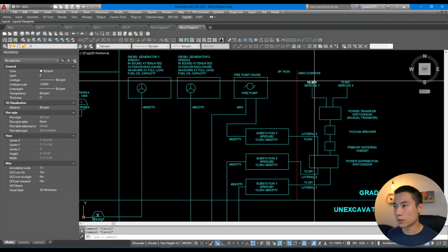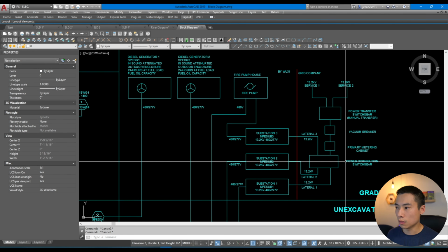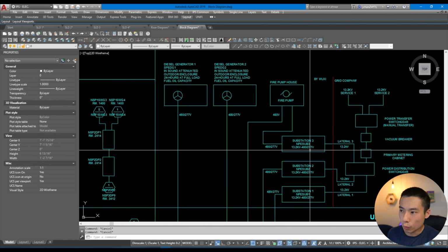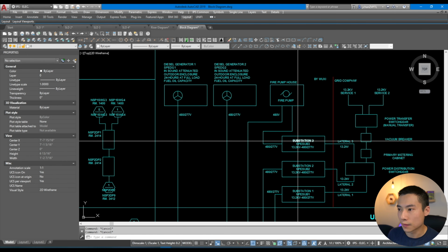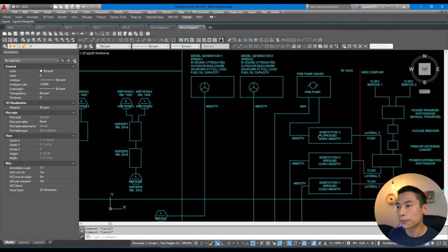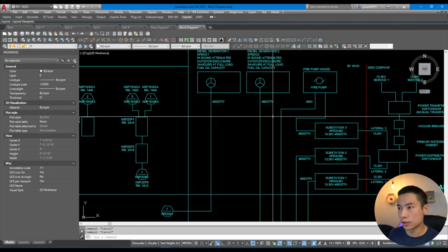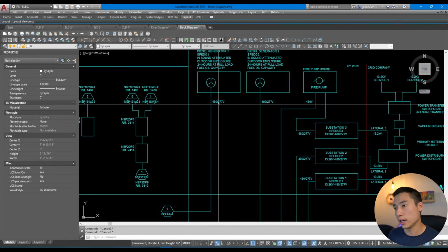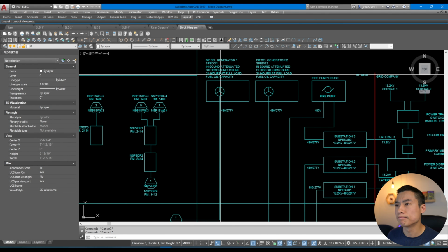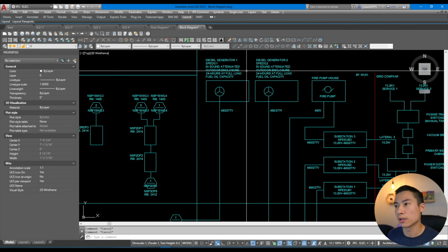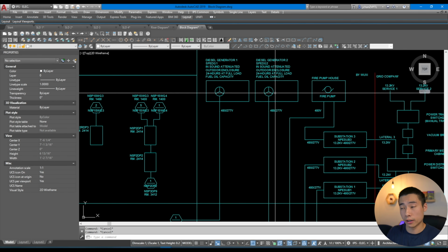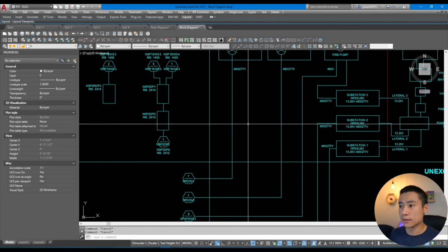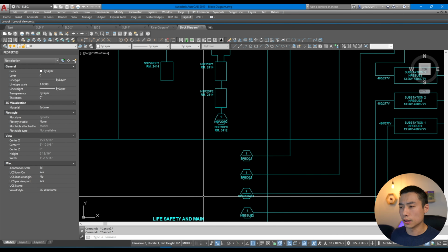Like out here, you can see we have 2 utility services coming in. We have a distribution switchgear out there, and there's 3 substations. One of these substations is dedicated to the fire pump. I mean, that's pretty easy for someone to follow along. Looks like we have some voltages listed. So like, you know, from here, you can see that our generators are 480/277. I think we left out sizing. Yeah, like here we don't bother saying the size because it's already stated on the single line diagram. But you can see that they're located outside. They feed underground into the main electrical room.